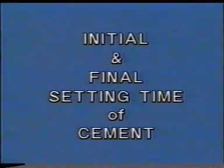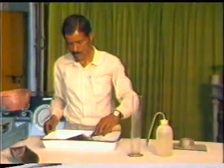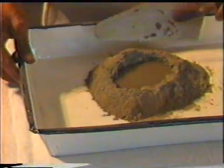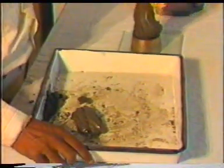Initial and final setting time of cement. Having determined the normal consistency of cement, let us now determine the initial and final setting times of cement. The phenomenon of setting refers to the start of chemical reaction between cement and water and loss of plasticity of cement paste.